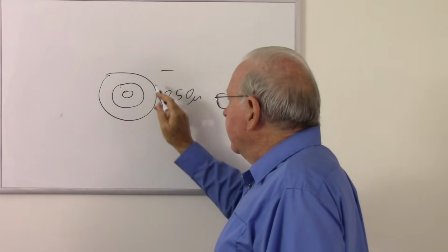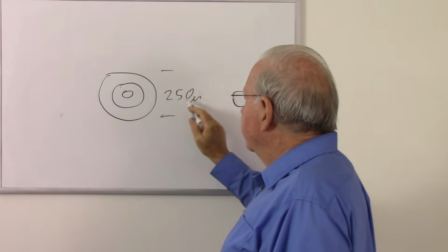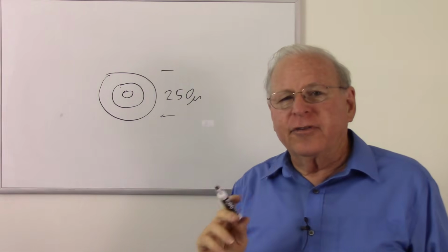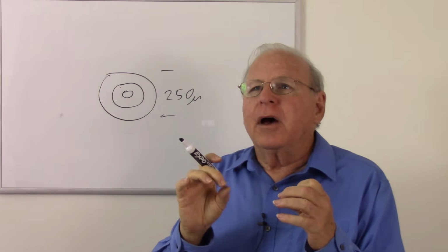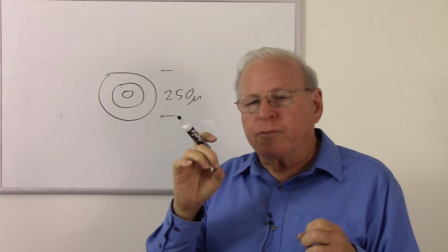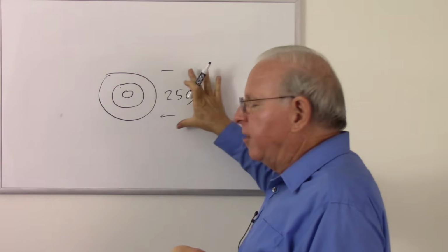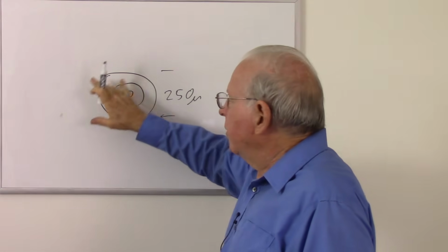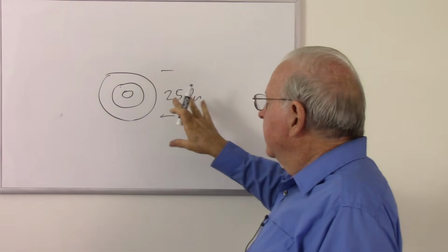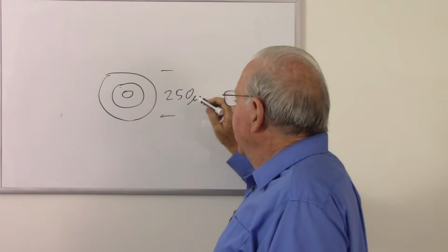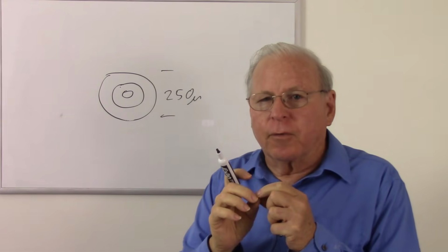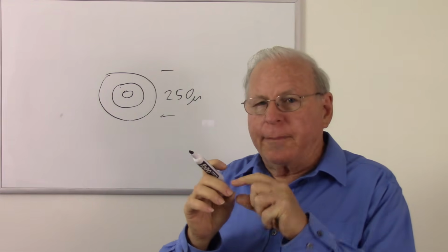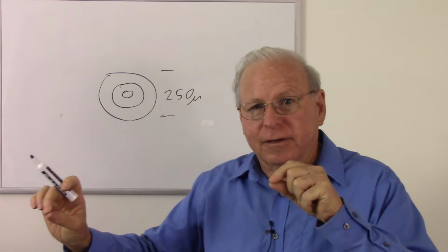Around that is a plastic buffer to protect it, which is 250 microns. And this is your basic fiber optic. When we talk about what's called loose tube fibers, that's what's in there: core, cladding, clear buffer, sometimes it's colored, but it's typically translucent, of 250 microns. And if you're working with loose tube fiber, you'll have these fibers in a little buffer tube.